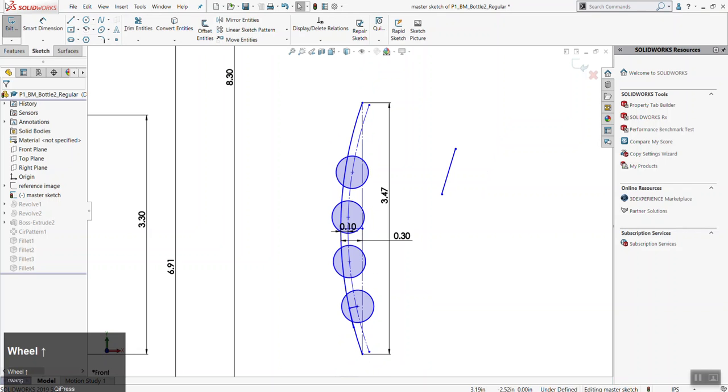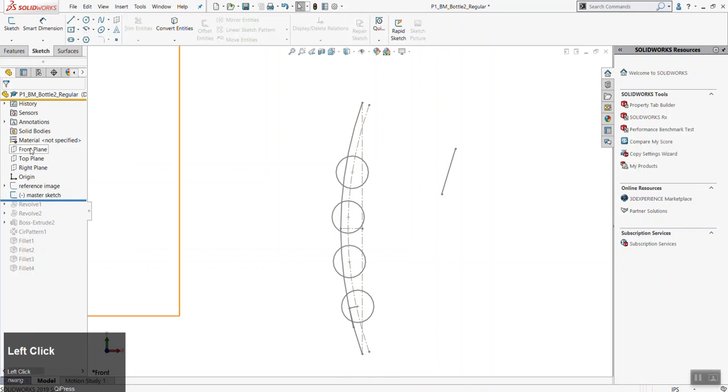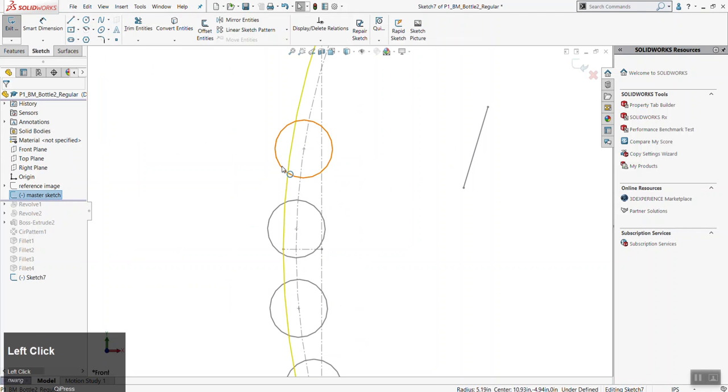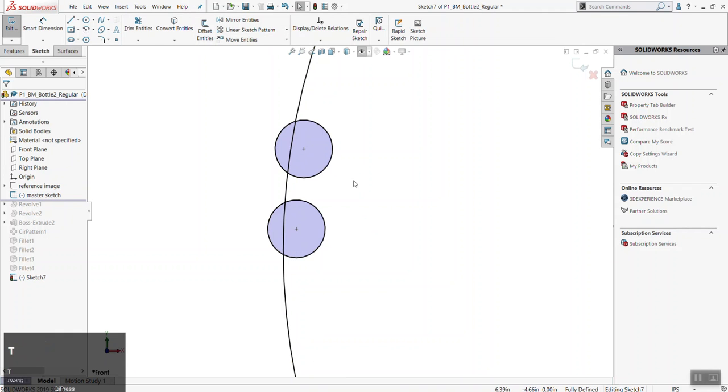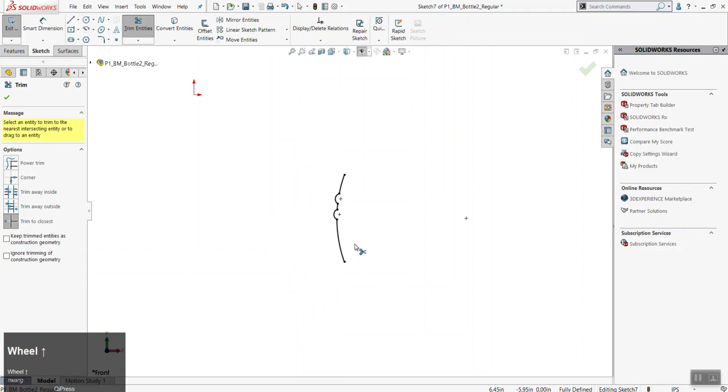And now when you copy this over, you would then use the trim tool. So I'm just going to roll this back. If I create a new sketch on the front plane now, I'll just copy these two for an example. You can just quickly hit T and just trim these out. And sometimes leaving the full circle keeps it a little more constrained. Does that make sense? Yeah, I know I'm flying through these. Again, if anyone wants to stay, I'm happy to answer individual questions after.